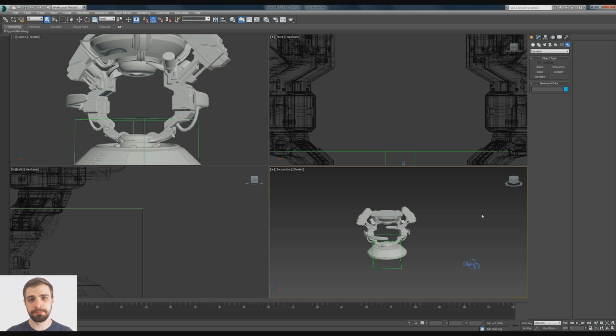Today I want to show you how to set up a clay render for your models using the daylight system, mental ray, and all inside of 3D Studio Max. There are of course a number of ways to do this, but I like this way, using the photometric lighting, because you get that warm lighting from the sun and the blue bounce light from the sky, and of course you have your ambient occlusion. And who doesn't love that?